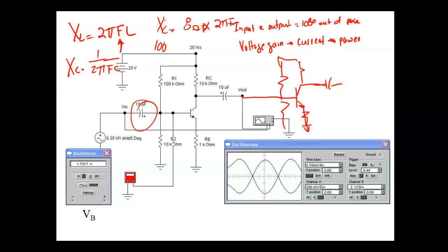So how does this thing check capacitance? It actually measures the capacitance. It has an oscillator in there that puts out a signal, and then it uses that to calculate.